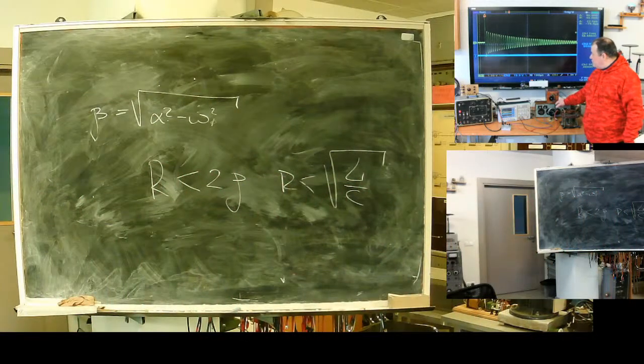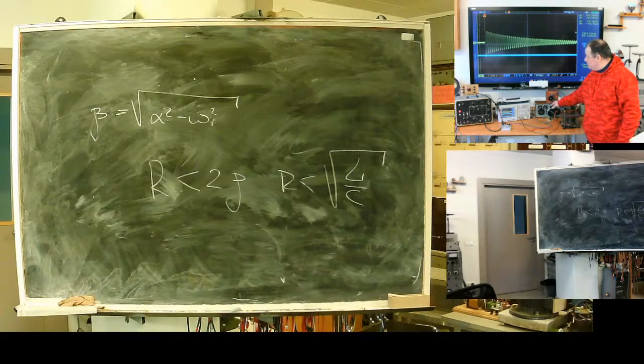Inductance change. I increase inductance, this means what? Oscillation frequency decreases. Why? Because the system is capable of storing more magnetic energy. More magnetic energy means greater inertia. Greater inertia means slower oscillation.